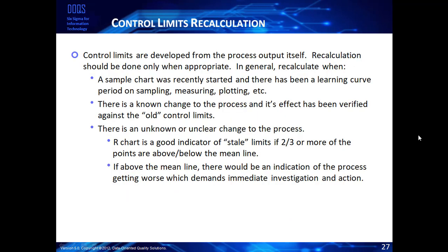Periodically, you'll be changing your processes. Often the reason you measure a process is so that you can spot a change in it. Not all change is undesired. If you're doing a process improvement effort, the whole point of what you're doing is you're trying to drive the process out of control for where it was to show that you've improved it. And once you show you have, you would end up recalculating the control limits to represent the new process going forward.